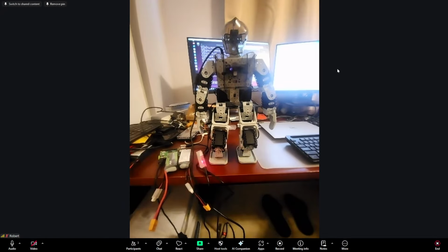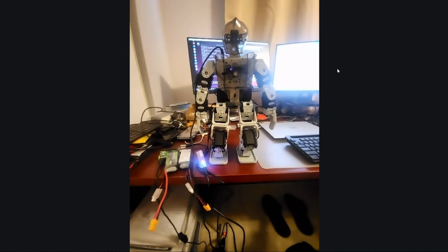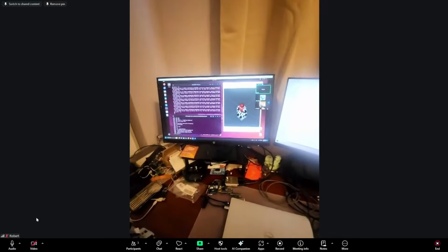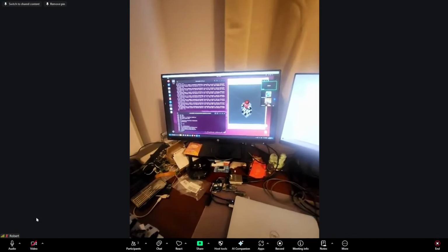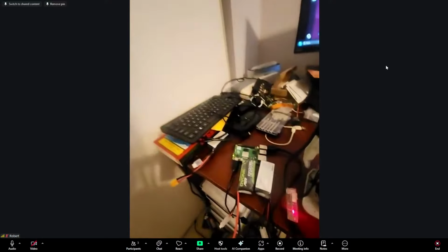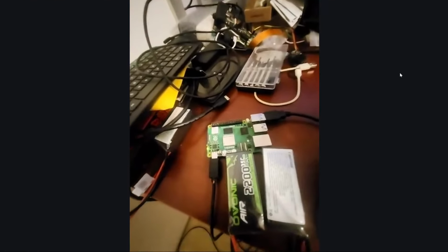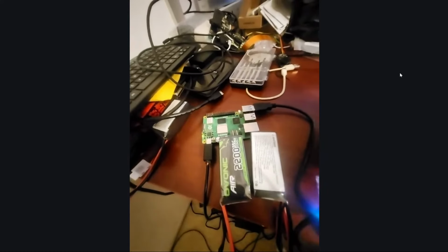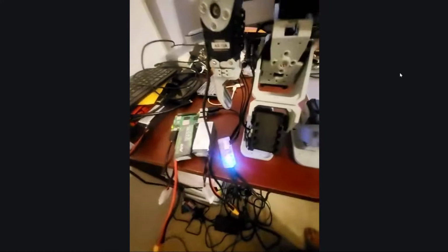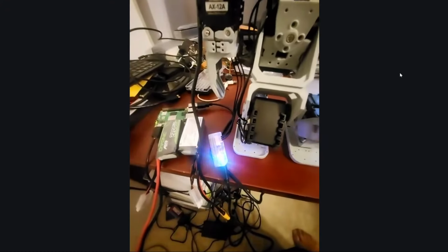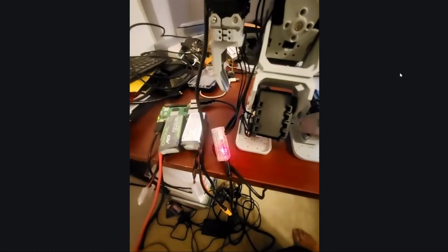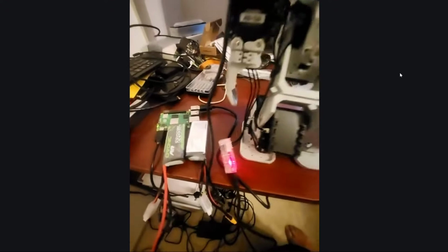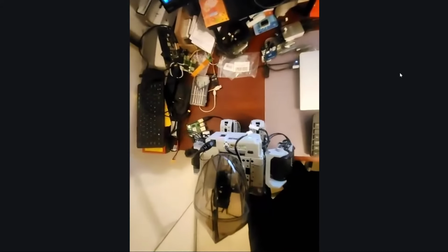So you see here is my real robot, and behind is my Raspberry Pi setup. I already set up the ROS, everything. And this is where I put my Raspberry Pi 5, held by the battery we had for the fastboard. And this is the U2D2 communication module connecting from the Pi 5 and then back to the robot, as I mentioned earlier.